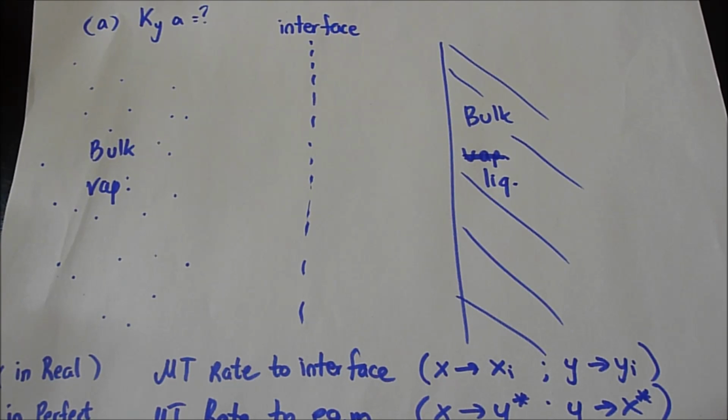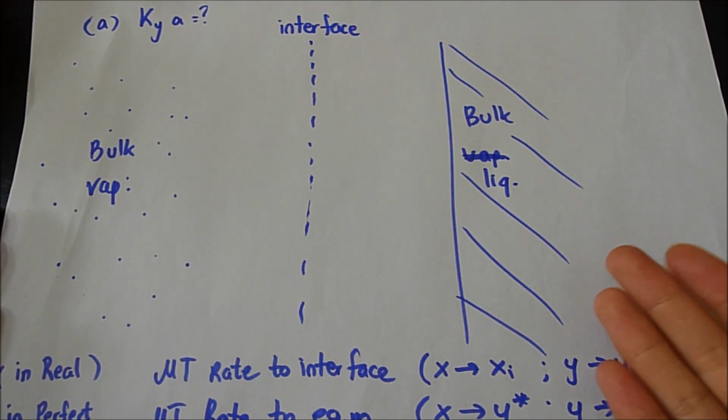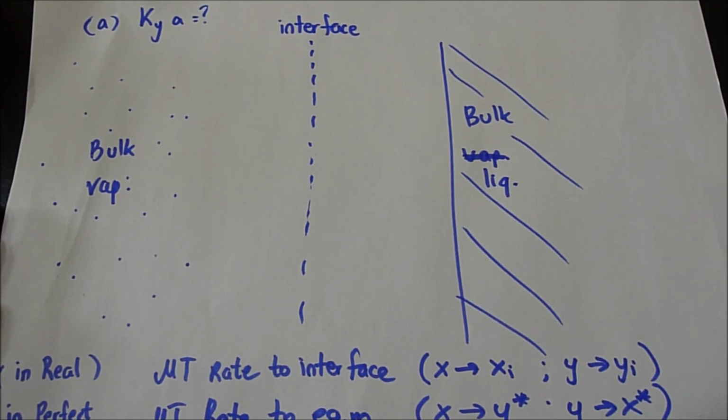In this case, this is the gas containing ethylene oxide, and this is the water to scrub the ethylene oxide. So they are meeting, they are going to be touching each other in order for the mass transfer to go on, using the packings, 1.5 inches of pall rings.